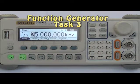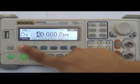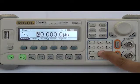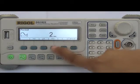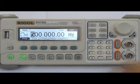Task 3 is to set up a sine wave with period of 2 milliseconds and a peak to peak voltage of 5 volts. Press the frequency tab to change it to period. In order to obtain a 2 millisecond period, just press 2 on the keypad and choose milliseconds. And then press period again for the function generator to show you the frequency of 500 Hz.